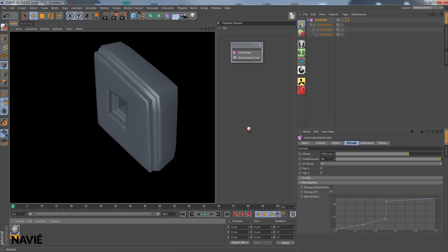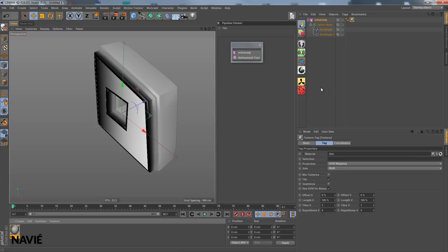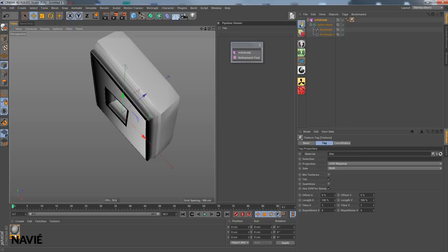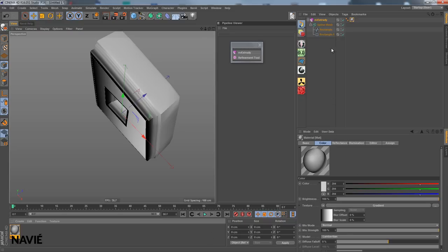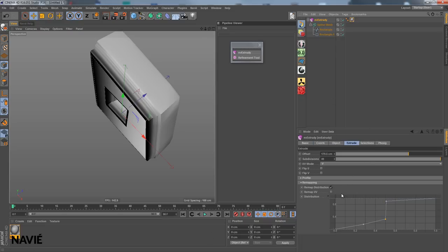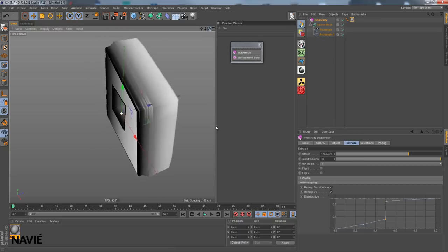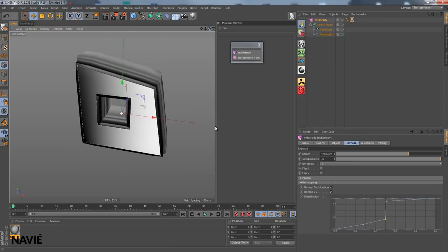now let's put our material back on our Xtrudy object again, and we can see now that our linear gradient has been moving with the polygons distribution actually. And turning off remap distribution will show us how they've been shifted with the polygon. And I can fix this by using remap UV, which will remap the UV data back to the original coordinates.